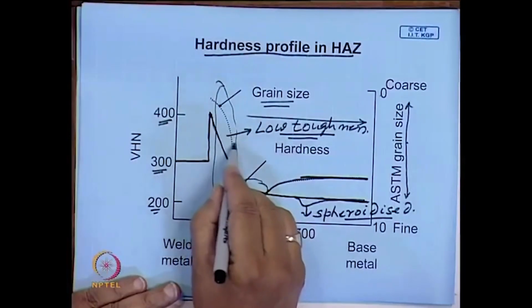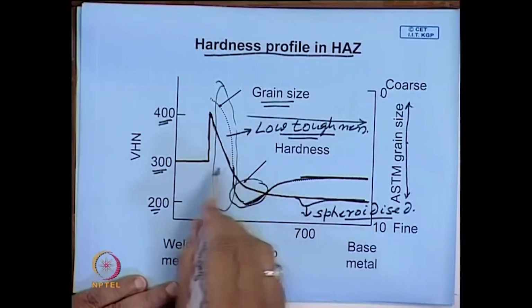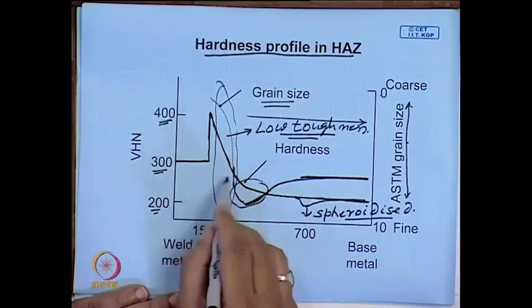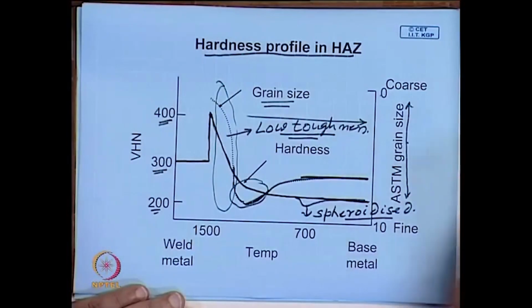If the welding electrodes are wet, they are not properly dried, if the slag layer on the weld pool is not protective enough, or the surrounding gas environment which is maintained is not protective enough, this hydrogen can diffuse into these regions. We may not see the crack immediately, but after you have welded and leave it for some time, you find there is a delayed cracking. Hydrogen relates to delayed cracking, which is a major problem.